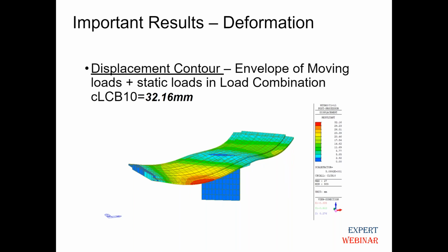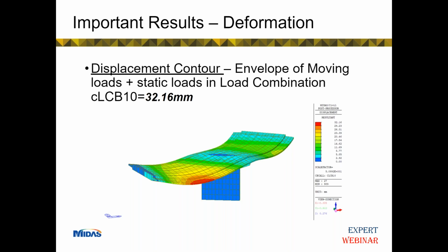And of course, you can even get the plate forces. You can see here the moments, and they're accurately got. You can even get the average node moment, or you can get the moments of each particular element, each particular plate element. You can even get the stresses. You can get the stresses of the top or bottom or both. So with Midas, in just a click, you can get numerous results.